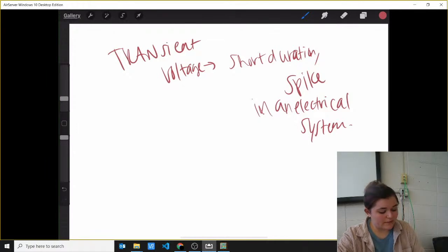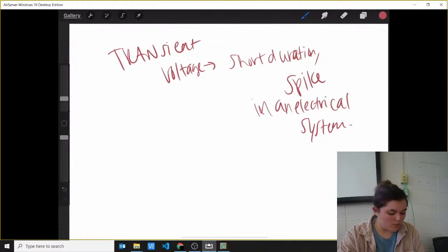Low energy level transients are transient voltages commonly caused when motors and equipment are switched on and off. They occur often, but do not cause immediate equipment damage. Low energy level transients cause malfunctions such as processing errors and damage to equipment over time. So the electronic circuits of an AC motor drive require protection against transient voltages. Protection methods include proper motor drive wiring, grounding, shielding from power lines, and surge suppressors.